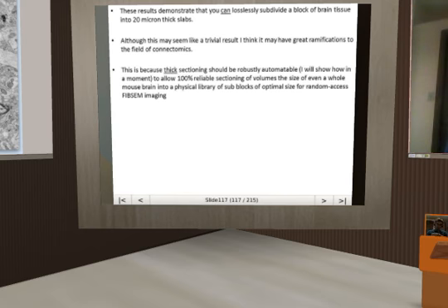If you were to try the focused ion beam technique on a block that was a millimeter wide, what you would get is the leading edge of the block being etched at a different rate from the middle of the block, and the end of the block would not be etched at all. It causes streaking effects and all sorts of things like that. So hopefully that answered the question. Yes. Okay.